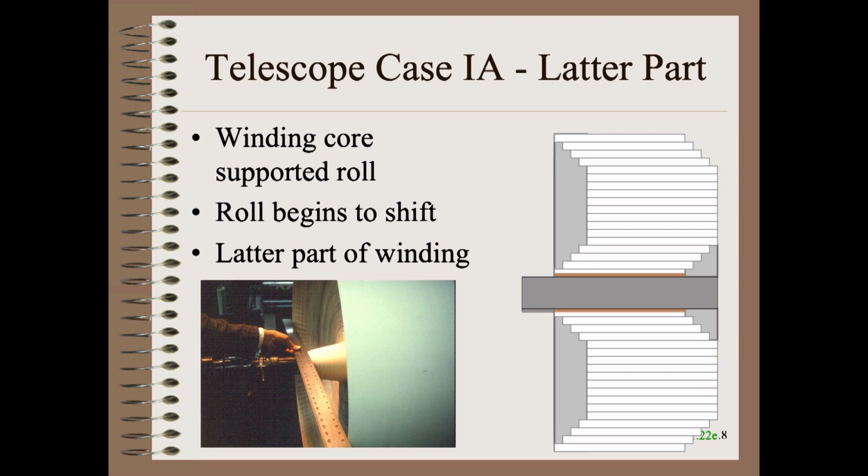We may also choose to measure the deviation from straightness as the distance from the roll edge to the ruler as a function of radius. Of course, we do that on both ends of this same roll. The sum of the measurements is width changes, and the difference between the two roll end measurements is telescoping.